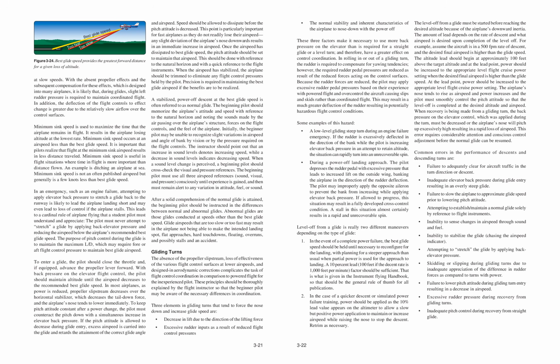skidding or slipping during gliding turns due to inadequate appreciation of the difference in rudder forces as compared to turns with power, failure to lower pitch attitude during gliding turn entry resulting in a decrease in airspeed, excessive rudder pressure during recovery from gliding turns, inadequate pitch control during recovery from straight glide, cross-controlling during gliding turns near the ground, failure to maintain constant bank angle during gliding turns.